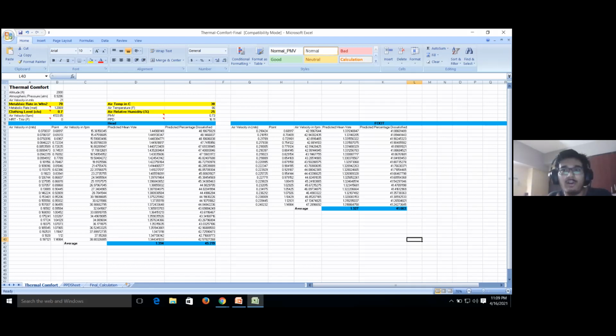So passengers will always feel a lower amount of pressure than what they would have actually felt if they were on the ground. And this will vary. For example, if you're at cruise level, you'll feel the pressure that a person would have felt at a height of 5,000 feet. This is what we obtained from our literature surveys. 5,000 feet is what we have taken. It can be altered as well.